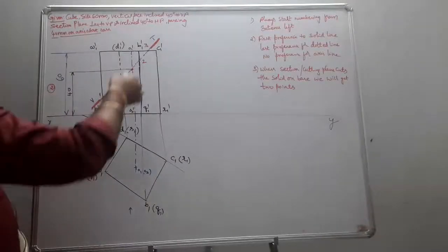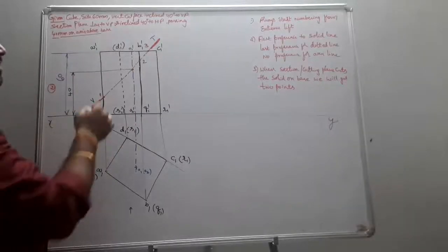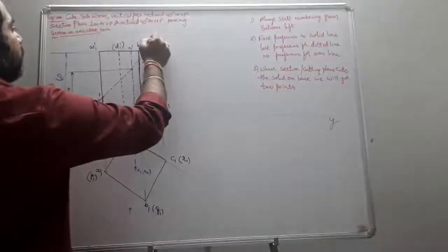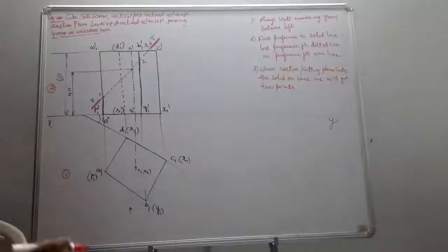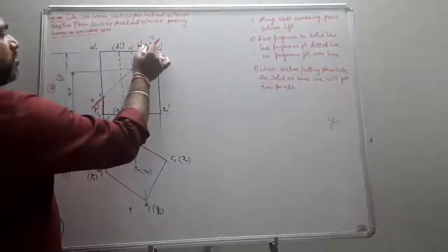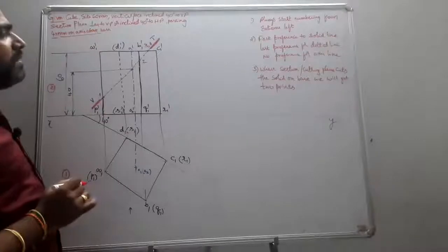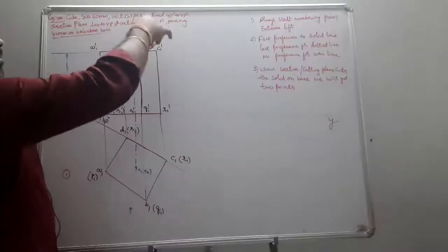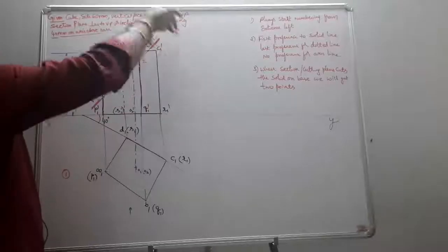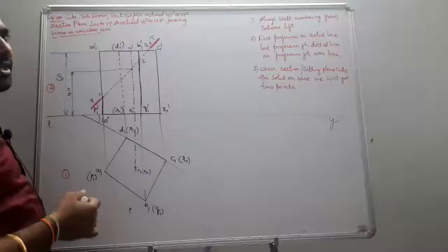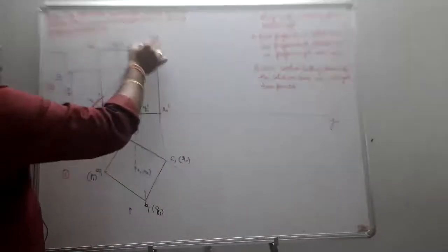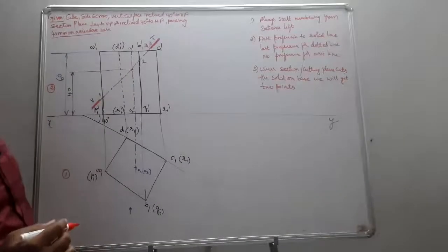And next, start from the end point, and we start here. So that means 3, 4. Why 3, 4, sir? You see this. BC is going to be your visible base edge, so I obtain my point 3. And backside you are going to have your CD edge also. It is also going to be cut by this cutting plane. So the numbering is given as the second number, that is the common point, as point 4.